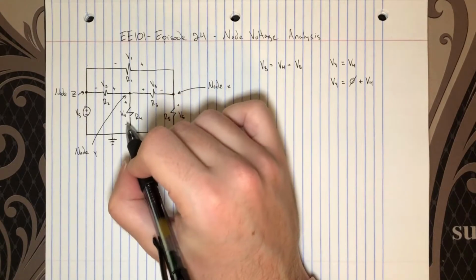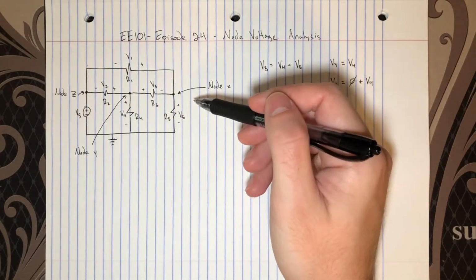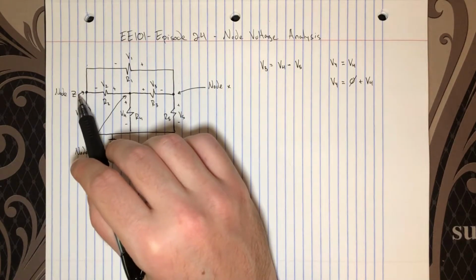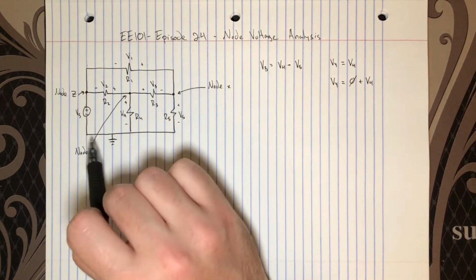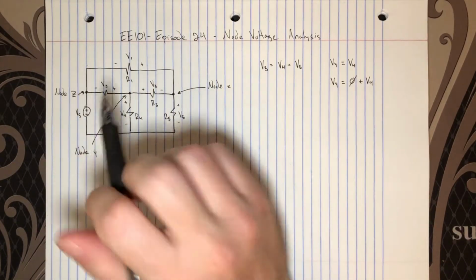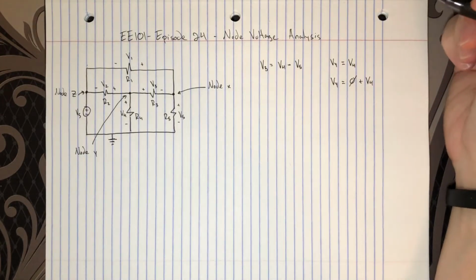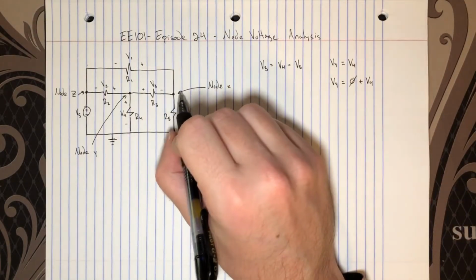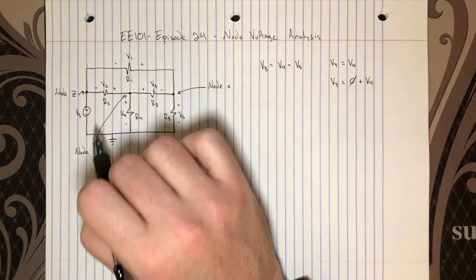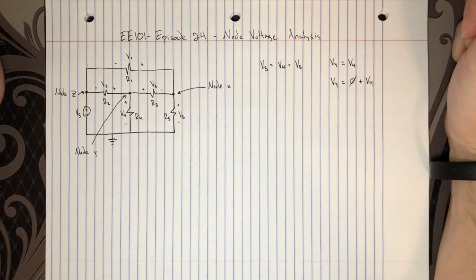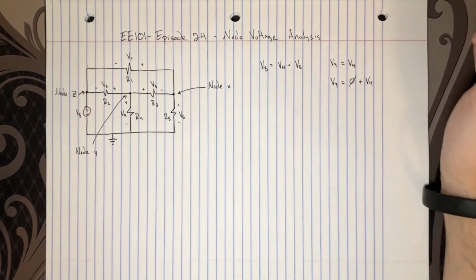Vy is really just V4. In that same way, Vx is just V5, right? And also Vz is just V source. It's whatever the source voltage is. Assuming that this is ground here, you just step up by the source voltage, and that's the voltage on that node, as people will say. So you might be interested in finding the voltage Vx as a function of maybe Vy or Vz. And that's a similar concept that we've dealt with before, but you'll find that things just become potentially easier as you move into complicated, messy circuits.